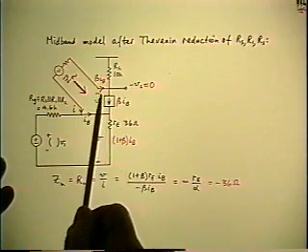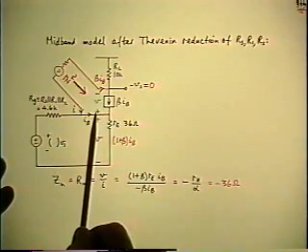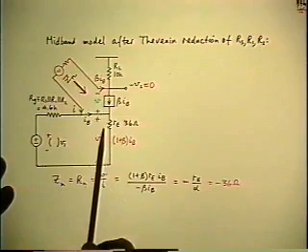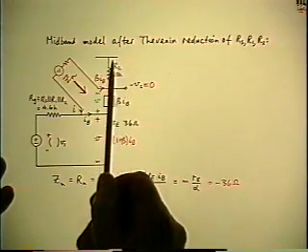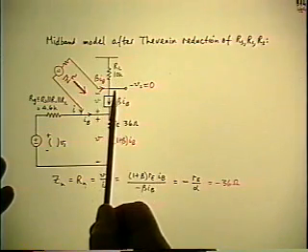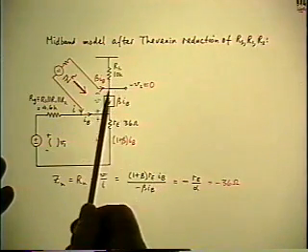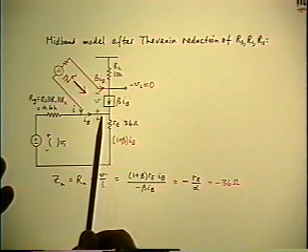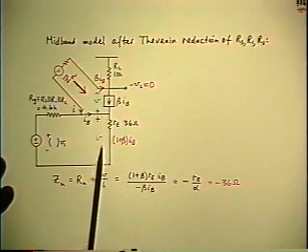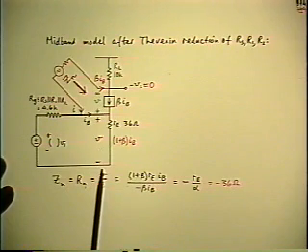The second step is, I want to know what the V is. The green V equals the red V, again because there is a null across the output. So this is AC ground at the output. If I step up by a green V from AC ground to the base, then I have to step down by the red V the same amount to get back to AC ground again.